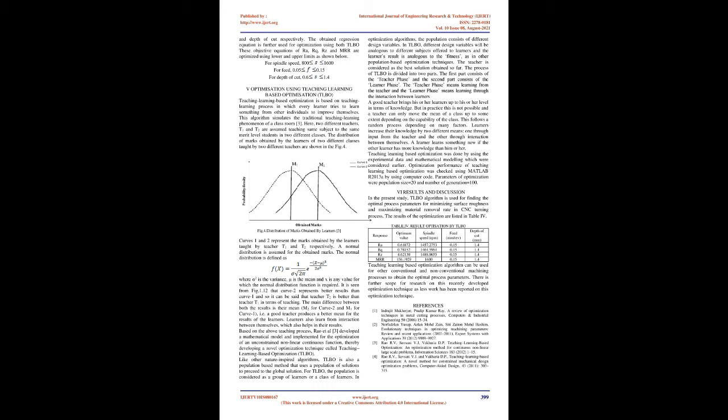Experimental setup and data collection. The machine which is used for performing the hard turning operation is shown in Fig. 1. The specification of the CNC machine used for the experiment is described in Table 1. Cutting tool used for the experimentation is a coated tungsten carbide insert of specification DNMG 150608. The specification of the tool holder is PDJNL2020K10. Workpiece used for experimentation is an AISI 1040 mild steel bar of 60 mm length and 25 mm diameter.